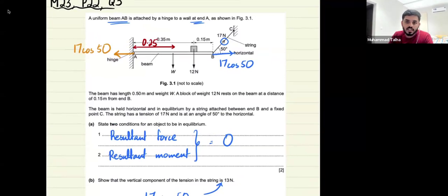All right, so the idea here is this. If I move this weight closer to the beam, this distance has reduced, right? And because this distance has reduced, what you used in a previous part of the calculation is that both of these are producing clockwise moments. So the clockwise moments go down.